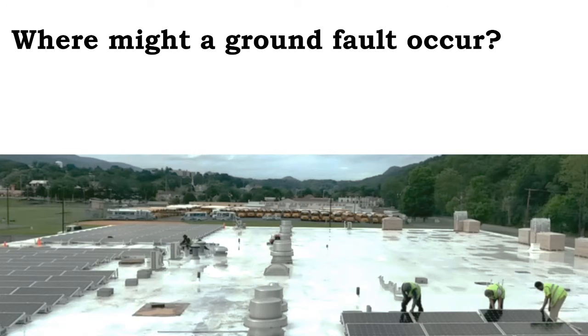Ground fault is not an arc within the circuit; it's a fault to ground. And so, let's say you're installing a solar array, and you're doing good wire management as you go along and tucking the MC4 connectors into the frame. Let's say your cable management crew is coming behind the panel installation crew, and a flash flood occurs, and they didn't get to some panels that have some connectors dangling down, in a puddle.